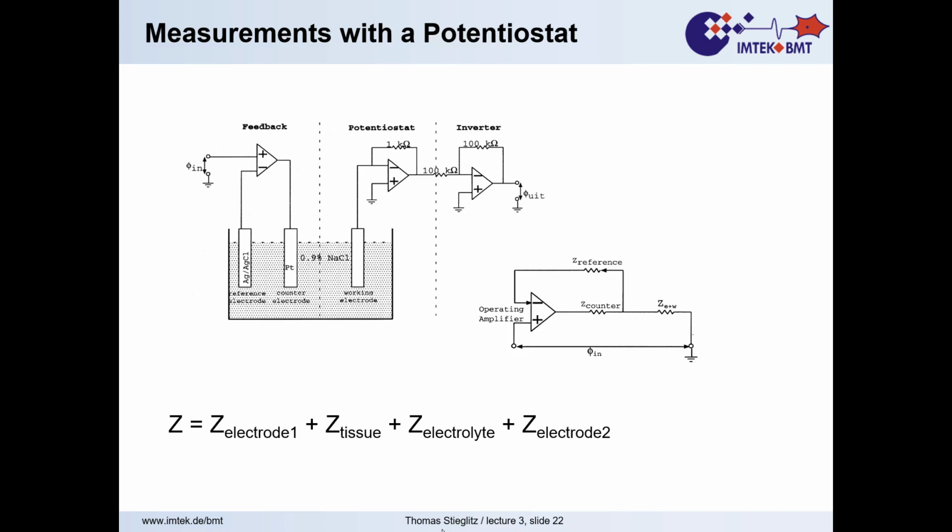Matching means that we have the conjugated complex impedance as input of the amplifier as the impedance of the electrode is. Then we have the best power transformation in between. Then you would need the Bode plot of that, because you want to see where it goes.